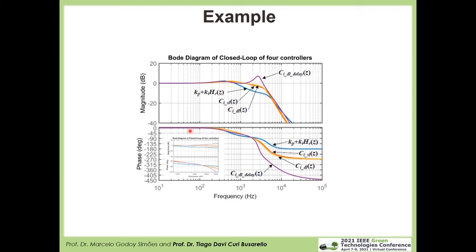And this information is quite good. We need to plot our closed loop system, considering the whole system and the designed controller, and we can verify if our bandwidth is satisfactory and presents the results that we are expecting. In this case, they are good, and then we can consider that the 4 controllers are considerably well designed.